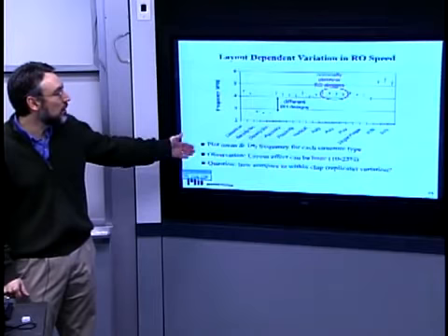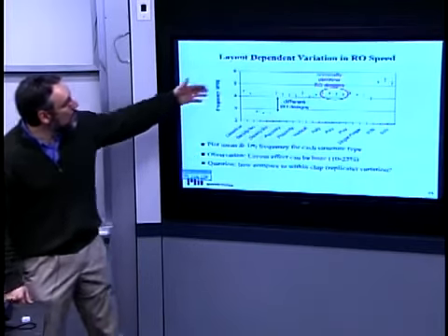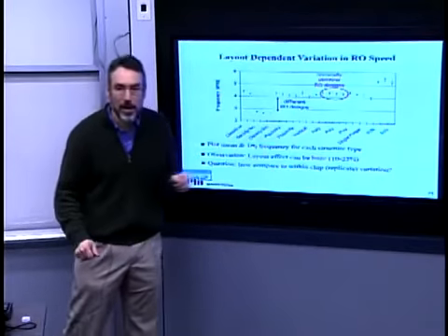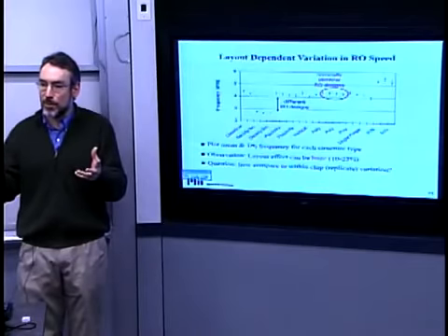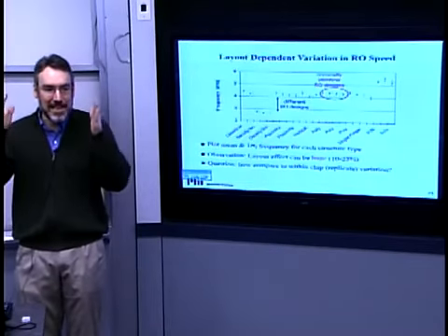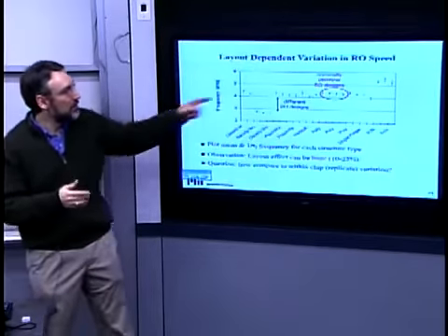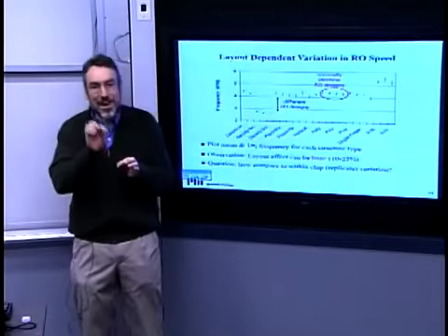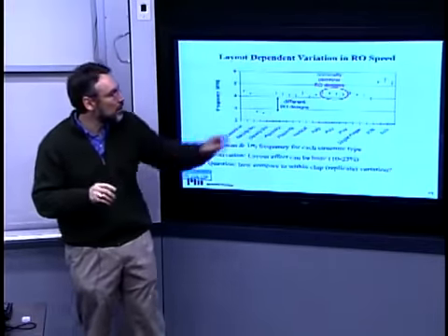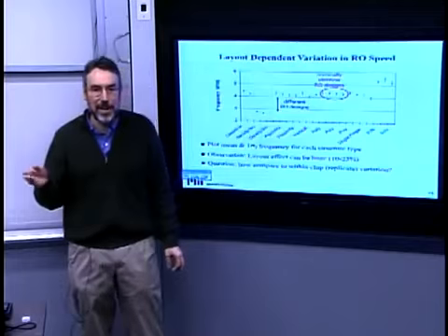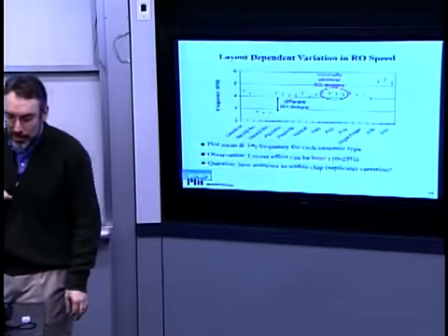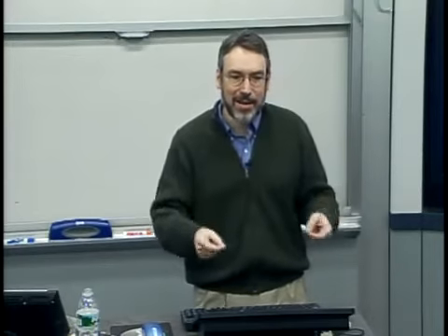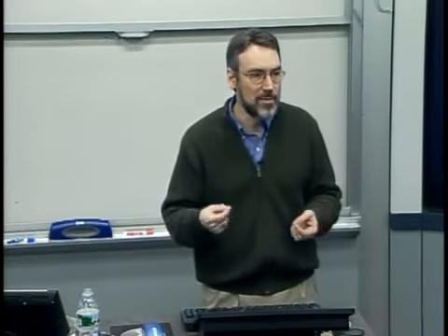And what's interesting here is that many of these ring oscillator designs are, from the circuit designer perspective, they think of them as identical. But in fabrication, because of neighborhood or nearby structures, in fact, there are slight deviations. So nominally identical transistors may, in fact, have substantial, systematic, highly repeatable effects.